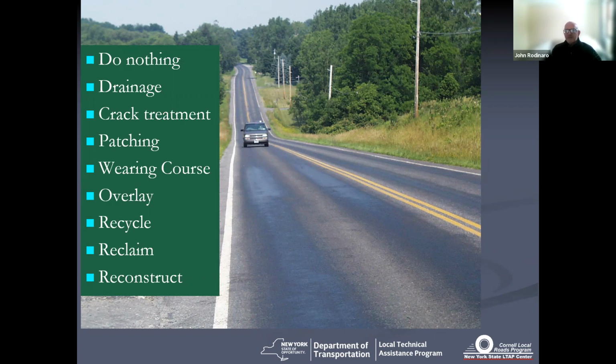The one thing you've got to think about is you're going to have to alter or modify your mix design, because you've got liquid asphalt at the surface, so you're going to have to adjust that mix design to account for that liquid asphalt. In many cases, you're going to have to think about an overlay, or depending on whether you've got some structural issues, you may have to mill and fill. We had a lot of problems like this on some DOT roads in the early 2000s, and we ended up doing a lot of 1.5-inch overlays to fix them.